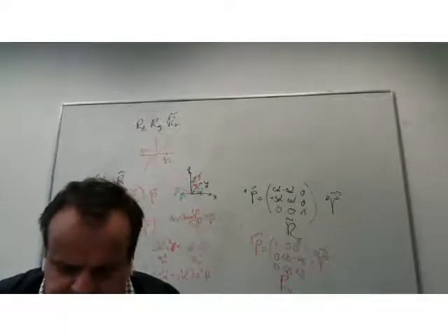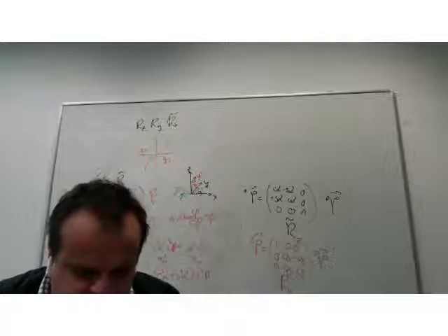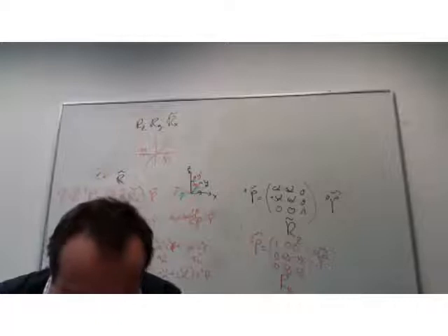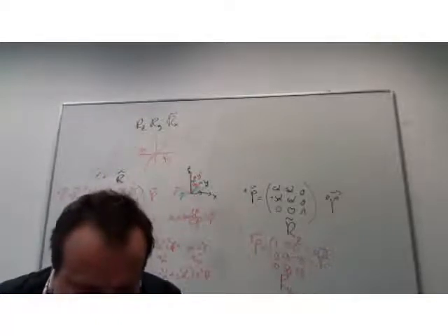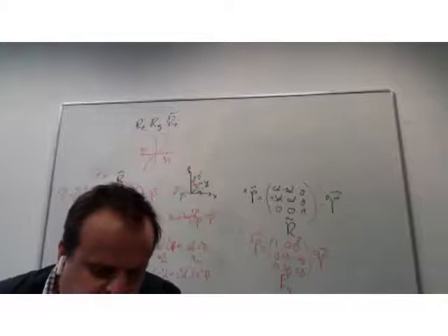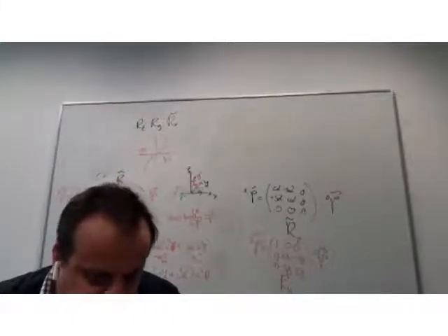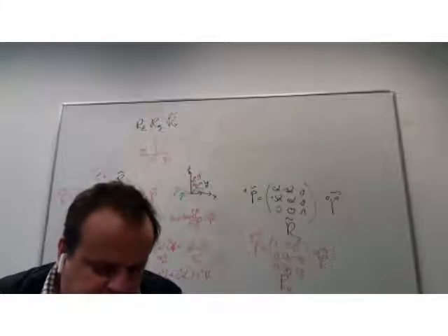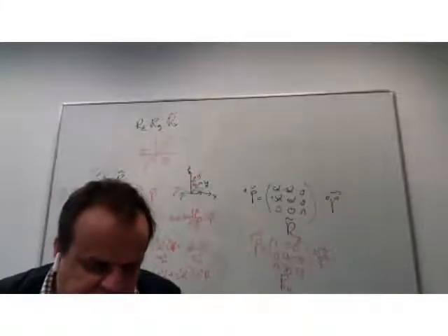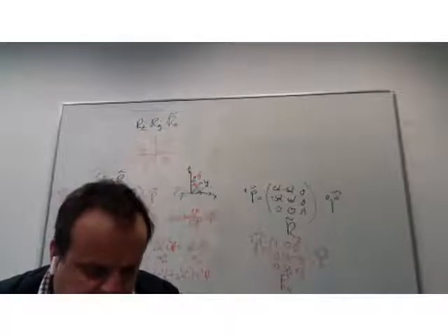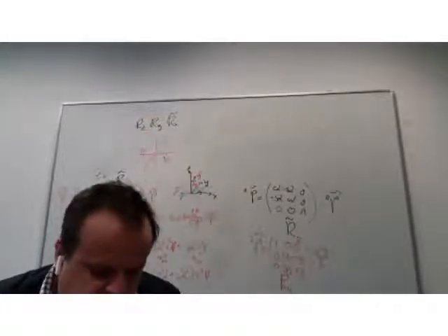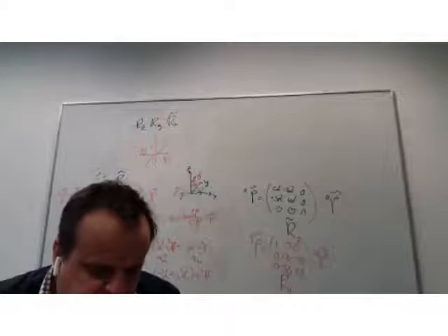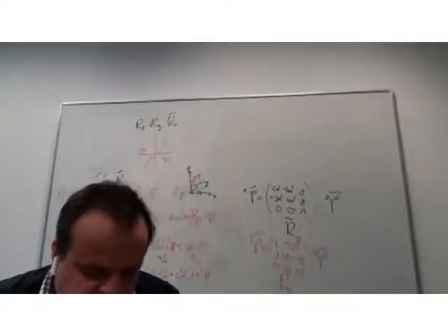So as we see here, now using the arcus tangent 2 function, if we plug in minus R31, then we have the sine typical expression, and this gives us a cosine beta expression. After that, what we plug in here is, of course, our numerical values. The matrix in reality is just 9 float values, which we use to do the calculations here. And from these 3 float values, using the arcus tangent 2 function, we get the beta. Once we have beta, we can calculate also the alpha angle.